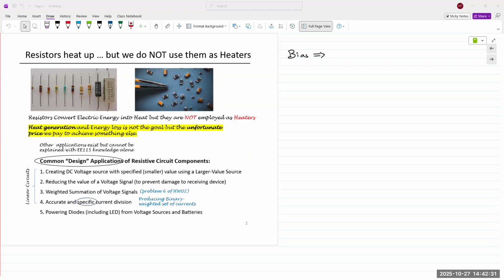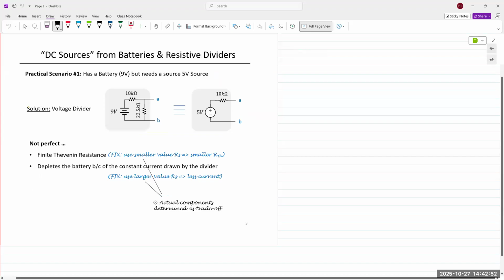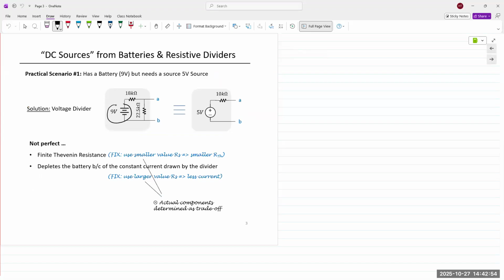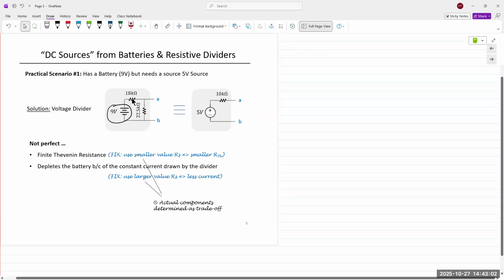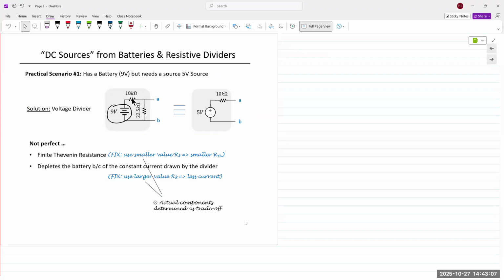And of course, because of current limiting and series connections, we can create voltage divider networks where we can take a single specific voltage source, create a resistive network divider, and we can obtain multiple voltage outputs from that circuit. So case in point was the previous Thevenin example where you have a 9-volt battery source and you wish to obtain a voltage other than 9 volts. Then we simply use a bunch of resistors connected in a series configuration, and we can obtain multiple voltage outputs.